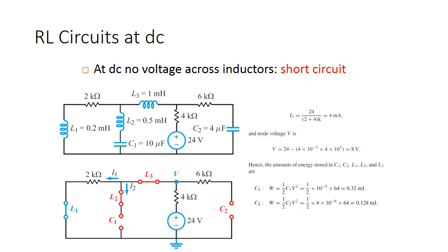Once a capacitor is totally charged, it acts as an open circuit so that current can't flow through it anymore. And that's why we can calculate the energy equations W, because they're fully charged. Now, if you catch this before the capacitor is fully charged, you get some current that can flow through, and you also get some amount of energy stored in the capacitor, but not the maximum amount, which is what we see right here.